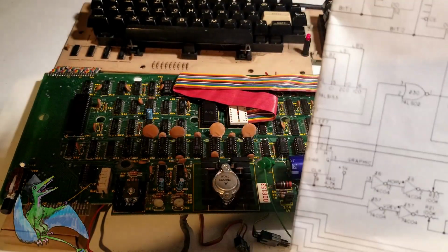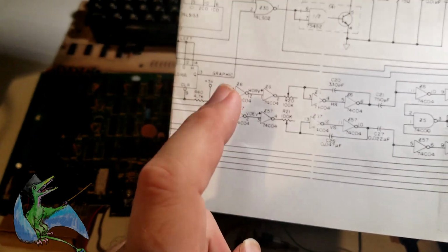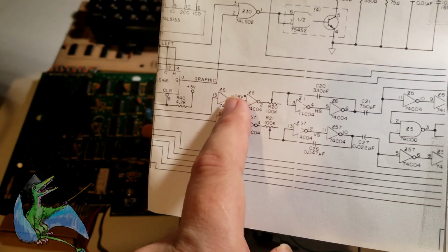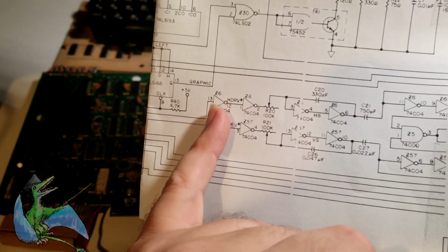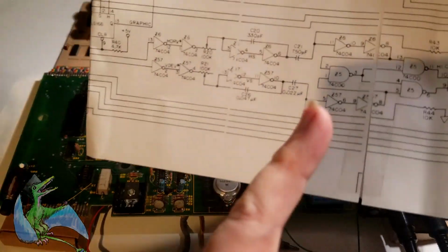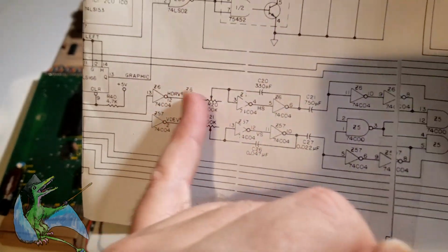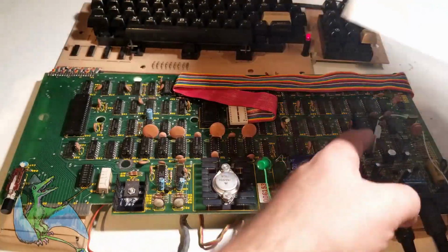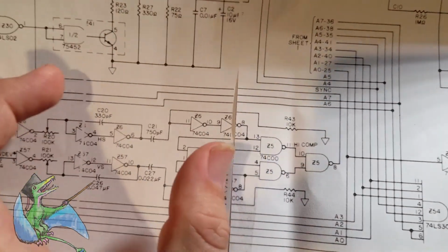I initially had one of the probes on pin 13 here, looking at the TTL signal. But to get a better, cleaner look, once I determined this part was working, I stepped all the way through and put a probe here, and a probe here. So the white probe is actually here after we've accepted the H-drive signal and cleaned it up to a nice sharp CMOS edge. And the black clip is all the way over at pin 8, which is the end of this.